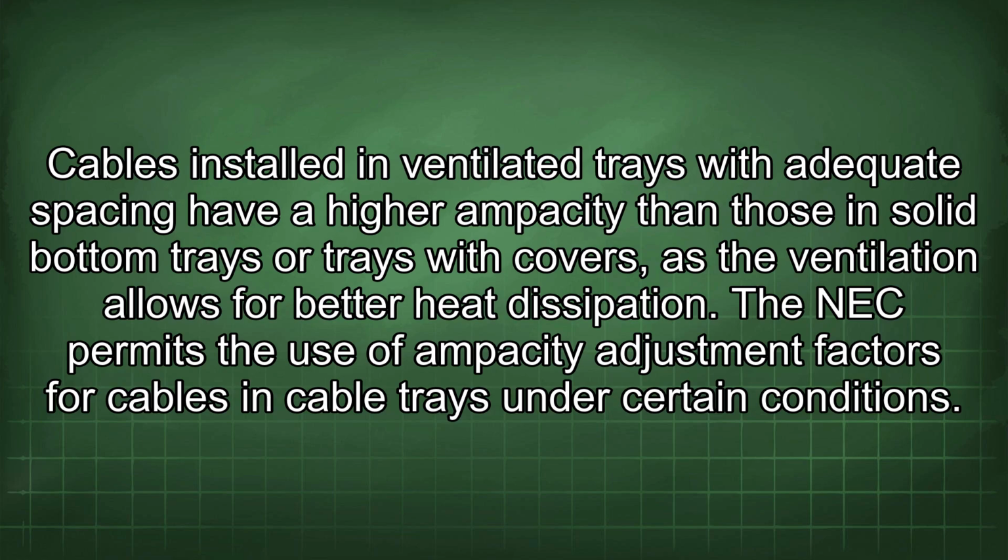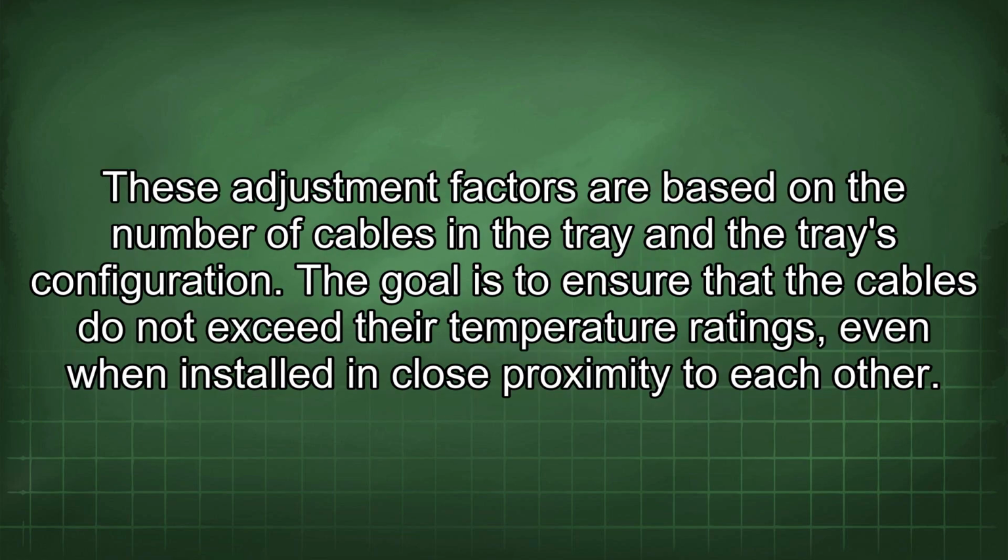The NEC permits the use of ampacity adjustment factors for cables in cable trays under certain conditions. These adjustment factors are based on the number of cables in the tray and the tray's configuration. The goal is to ensure that the cables do not exceed their temperature ratings, even when installed in close proximity